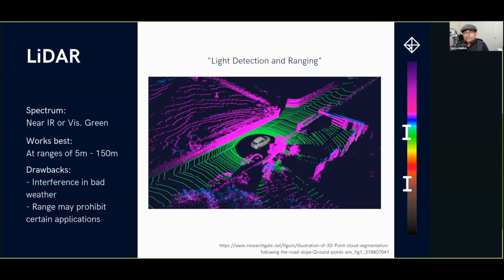So one other thing that comes into the picture often is, when you have transparent or even reflective surfaces, stereo vision falls apart, because stereo vision is based on the assumption that if you're looking at something, it looks the same from two different locations, right? But that assumption doesn't hold when you are looking at something which is reflective.